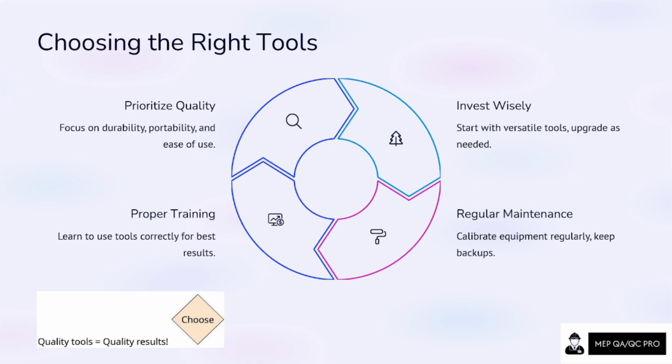The basic tools which we need to invest in include the gauge, checking the gauge for the duct, 18 gauge, 24 gauge. It depends on the job. Then you need to use the laser measurement. I know as of now you are using a basic measuring tape, which leads to time delay, taking measurements from here every time to ensure the work has been done as properly measured. But once you have this laser, you can easily go one by one and finish a 1 hour inspection within 15 minutes.